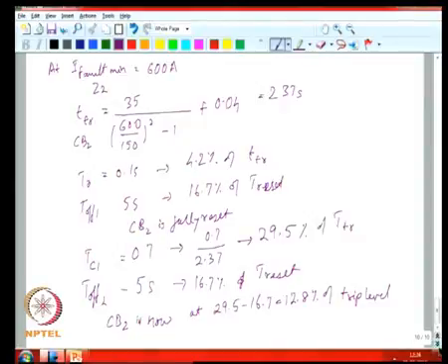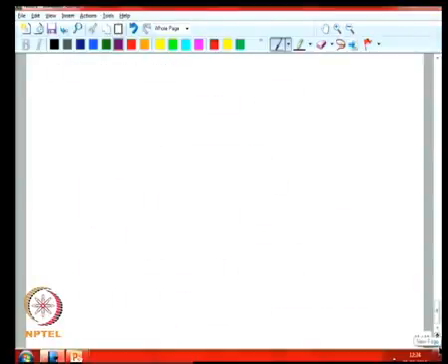If you look at the next duration of reclosing, which is for 3 seconds, TC3 equal to 3 seconds, this corresponds to 3 divided by 2.37 or 126% of trip time. So, again the circuit breaker is going to trip when it reaches 100%. So, it is going to trip definitely before the 3 second duration that you have. So, your actual tripping